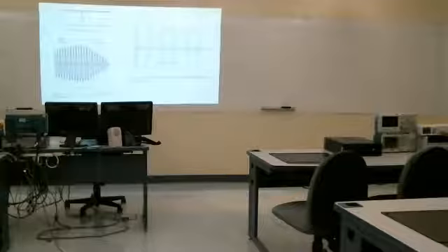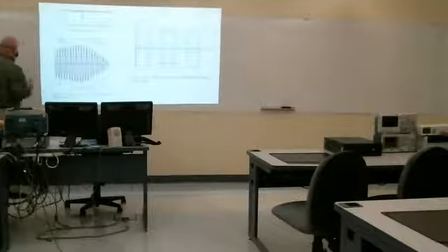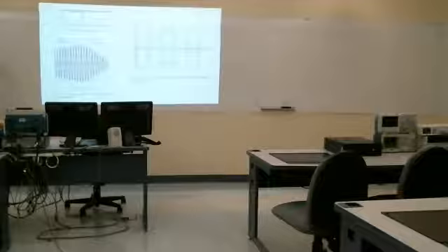You charge up the capacitor here, it starts to discharge, but you get another voltage hump, so it'll charge up the capacitor, and so you get something like DC out. Okay. This is pretty much the same, except with our AM waveform, our amplitude is constantly changing.